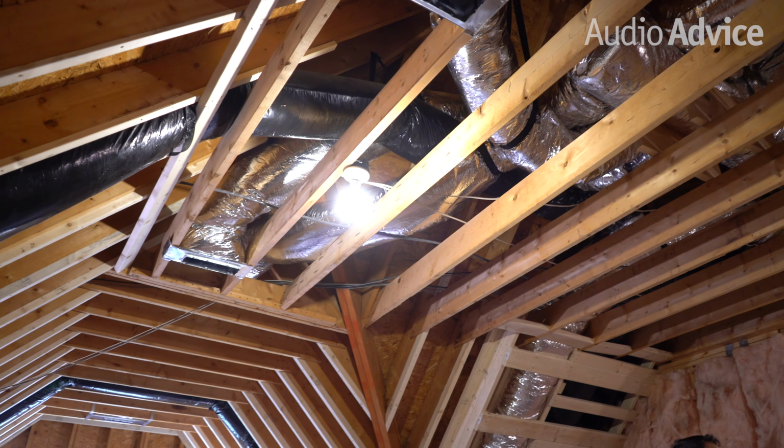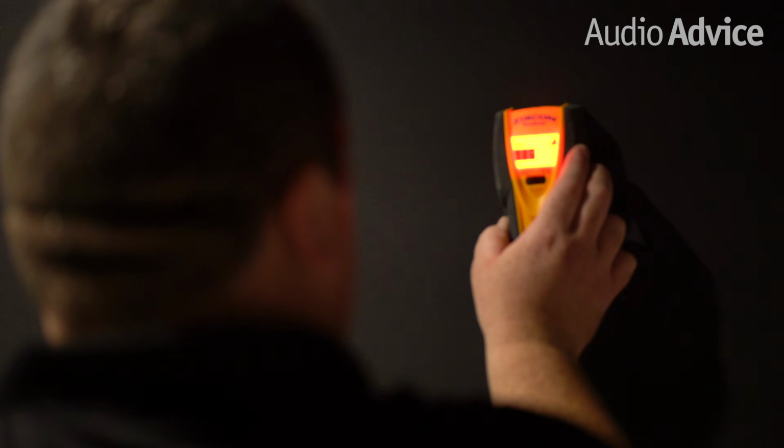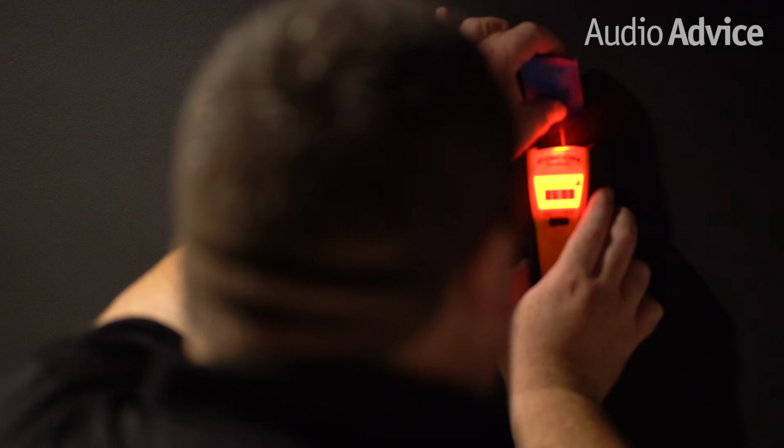If there's a stud in the way of where you need to put an in-ceiling Atmos speaker, we find it better to move them to the left or right rather than front to back to find the spot where they can fit in the ceiling between the studs. For side speakers, we usually suggest you move them slightly backwards, and for rears, move them further apart rather than closer together. If you have more detailed questions, jump over to audioadvice.com and chat or give us a call.